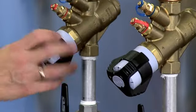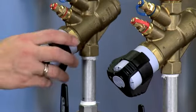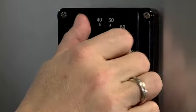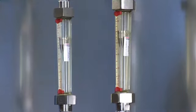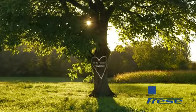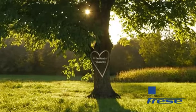If you expand the system in the future, there is no need to repeat the full commissioning process. Instead, just increase the pump speed to deliver the required pressure to the index valve, because the system will always be in balance.